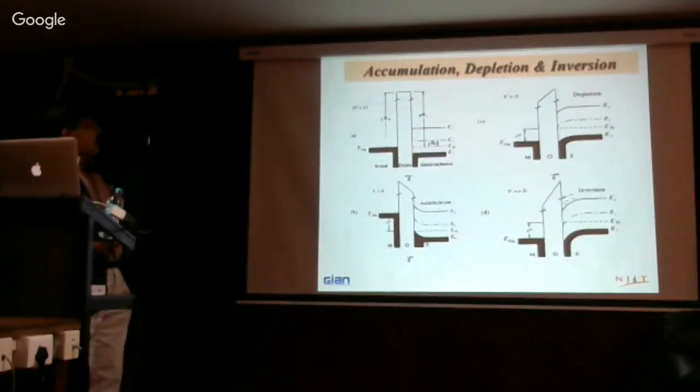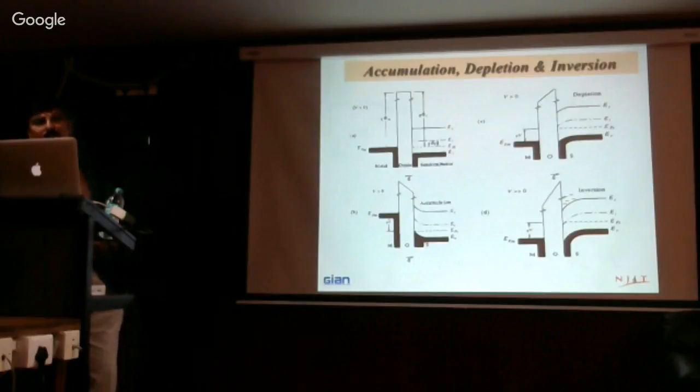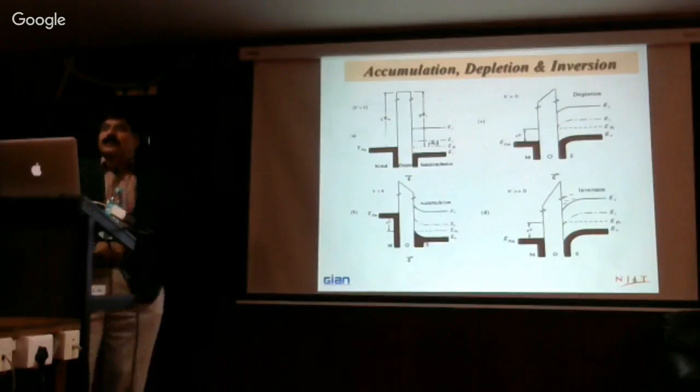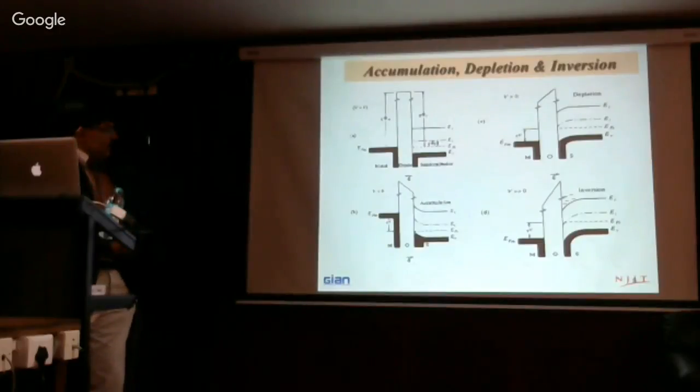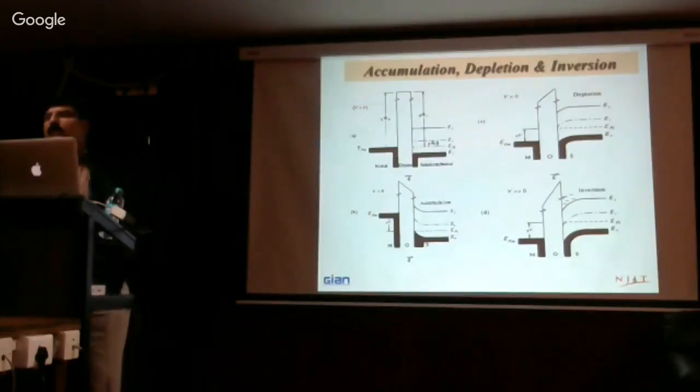This is the band diagram. If you have bands, normally assume the bands are flat to start with. Now, when you do the accumulation, this is a P-type semiconductor. What happens in accumulation? In a P-type semiconductor, a lot of holes come in. So that's why there is band bending. And the valence band goes very close to the Fermi level when the holes are at the interface.